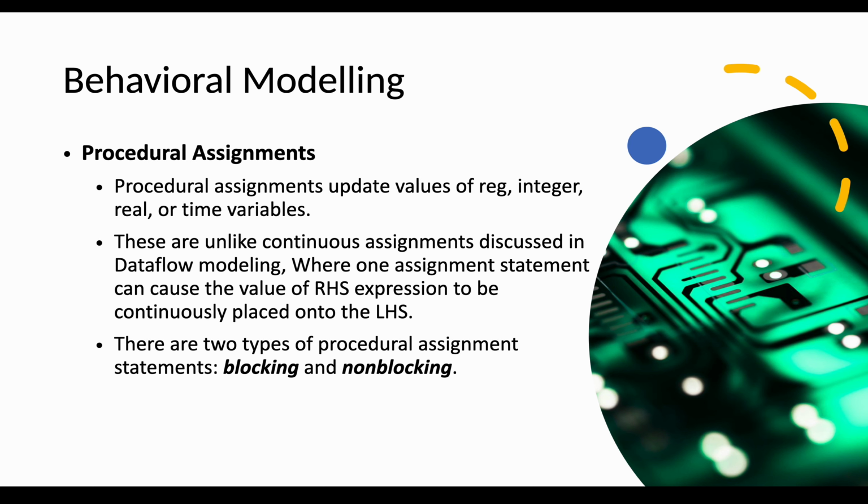Then we will discuss procedural assignments. Procedural assignments update values of register, integer, real or time. These are unlike continuous assignments discussed in data flow modeling, where one assignment statement can cause the value of the RHS expression to be continuously placed onto the LHS. There are two types of procedural assignments, blocking and non-blocking.